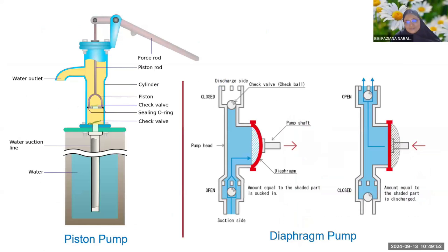These are really small pumps, looking not really like a cylinder but more like a plate. They are usually used in the lab or in a small working environment, and can be driven by pneumatic pressure. Essentially, these are very small metering pumps used to inject chemicals in very precise quantities.